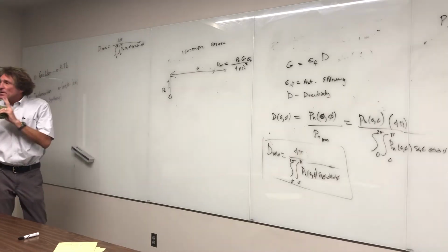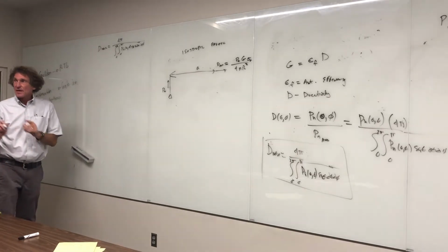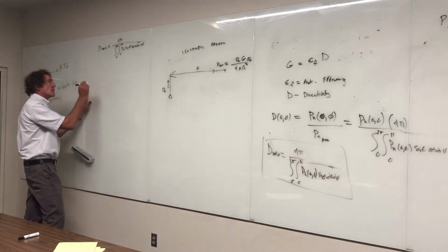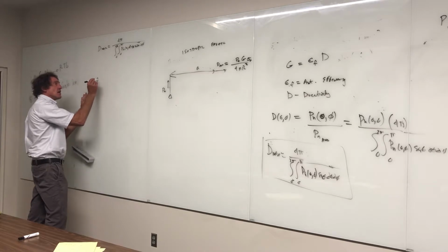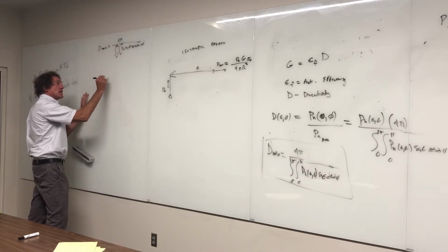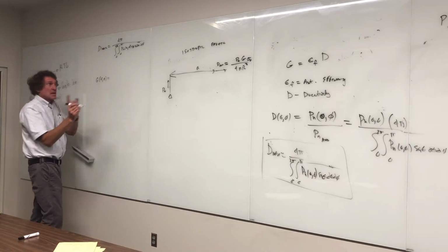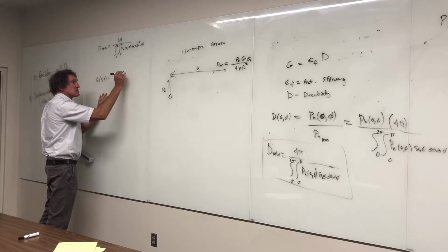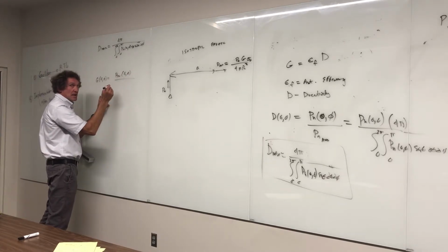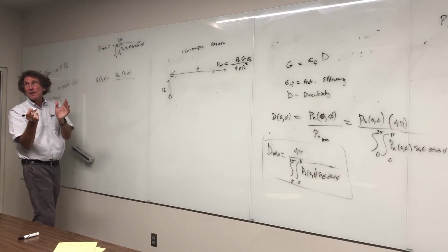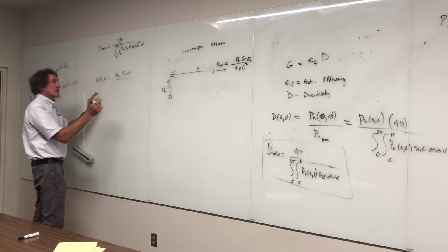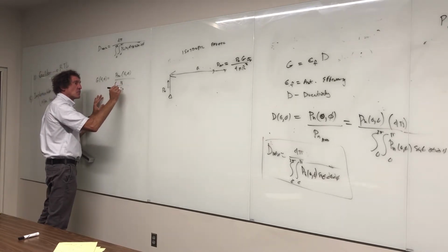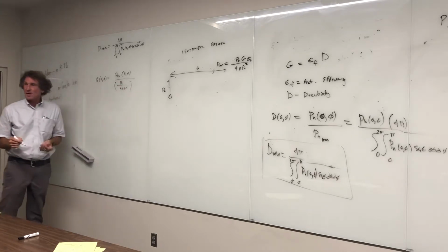I can tell you really the bottom line with gain and directivity. When I teach radar, I do it differently. When you talk about gain particularly, the gain of theta and phi, what it really amounts to is the average power density from the antenna you're using, divided by what the power density would be from an isotropic radiator. So what would the radiation be from an isotropic radiator? It would be P transmitted over 4 pi r squared. You follow me on that, class?